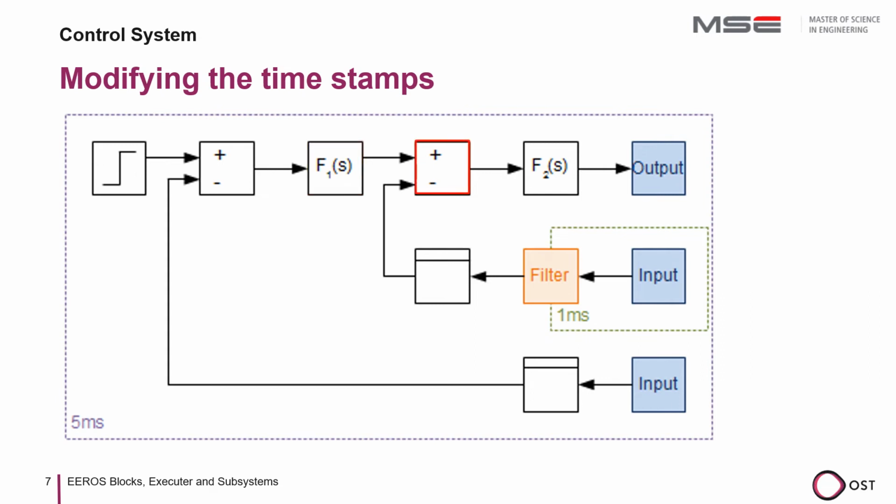If calculations are performed with several signals, the signals should be based on the same time base and have the same timestamps. Therefore, it may be useful to convert the values of the incoming signals to a common time base before calculating the algorithm of the block. Transition blocks have a clear influence on the timestamp. Let's look at a transition block from fast to slow.